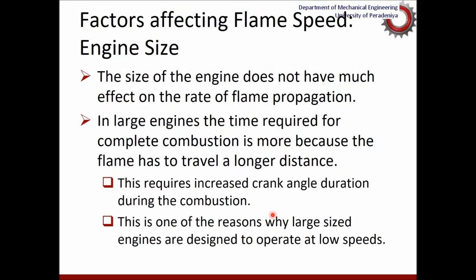And the engine size also matters for the flame speed. As you can guess, if the engine size is large, that means the flame needs more time to travel from one end to the other, or from the spark plug to the chamber walls. So the larger the bore or the stroke is, the more distance the flame needs to travel to burn the entire mixture. Therefore, you need more time.